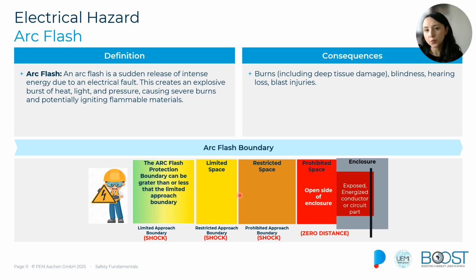When we move forwards to this energized conductor, you will find different regions, and the next region is the limited approach space.